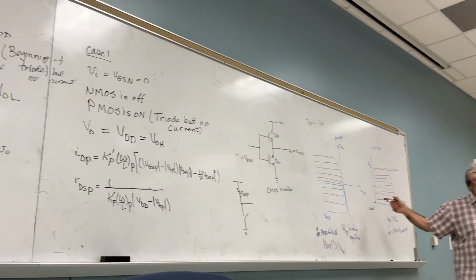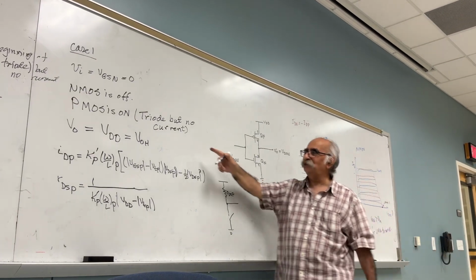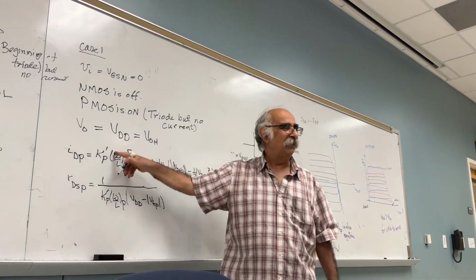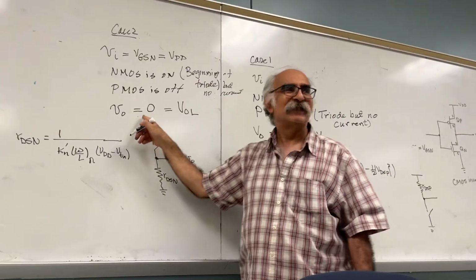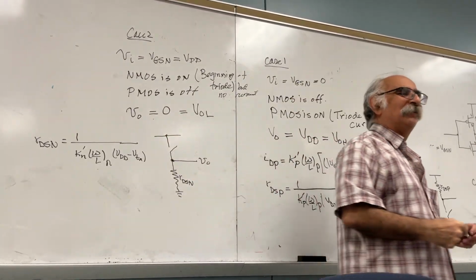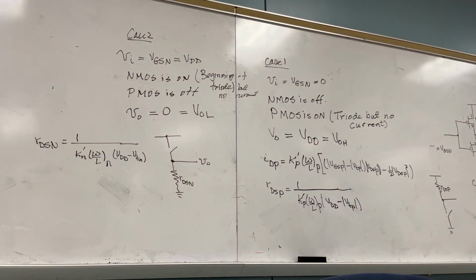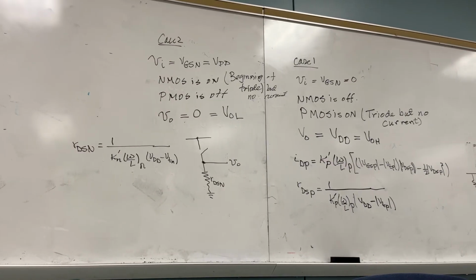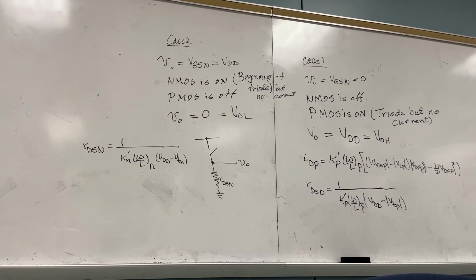These are the extreme cases. By the way, VOH is how much? VDD. VOL is how much? 0. Good or bad? Good. And answer me the following question. Is there power dissipation? No. Static power dissipation. I'm not talking about dynamic. Dynamic, we'll get to it.